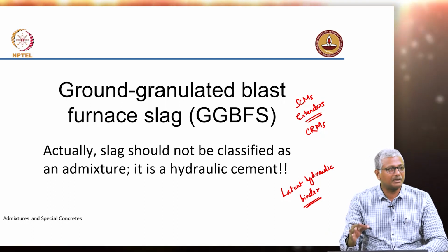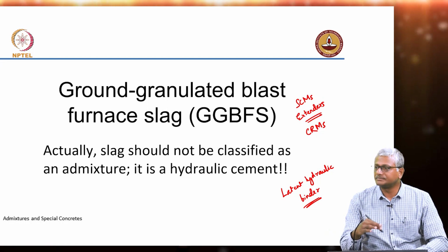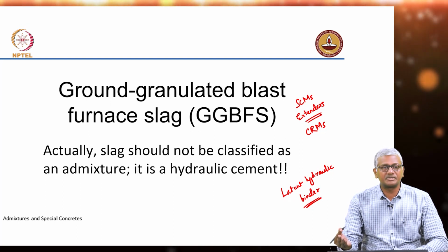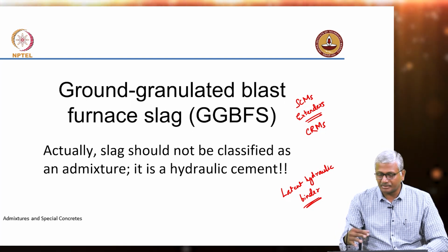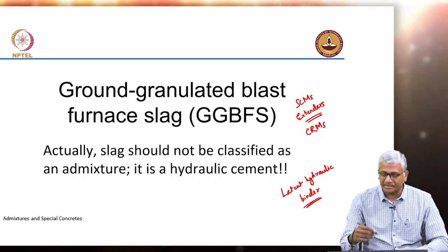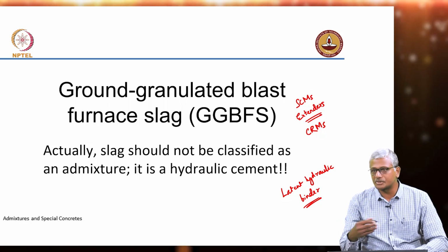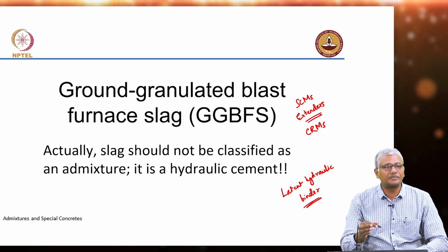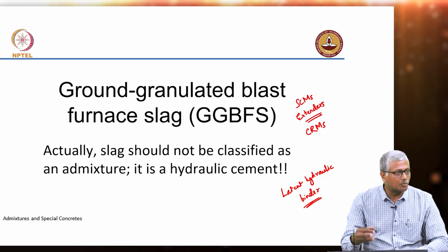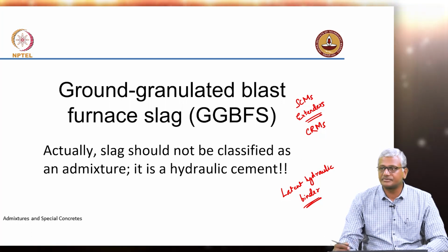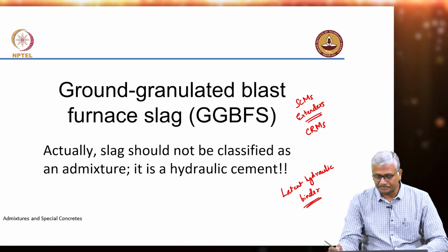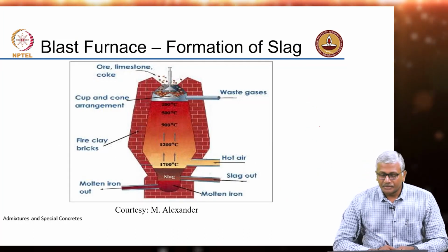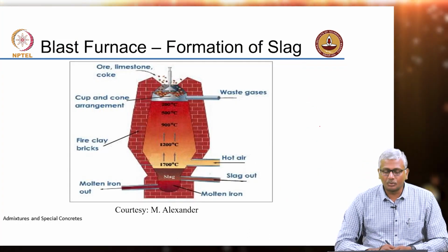Okay. So, you have to be careful about what the authors of papers and books are referring to when they refer to all of these materials. Extenders is a term that is used in Europe for defining the properties of special cements which have more and more of these mineral additives as replacements of cement, right. So, this is something that you know very well.